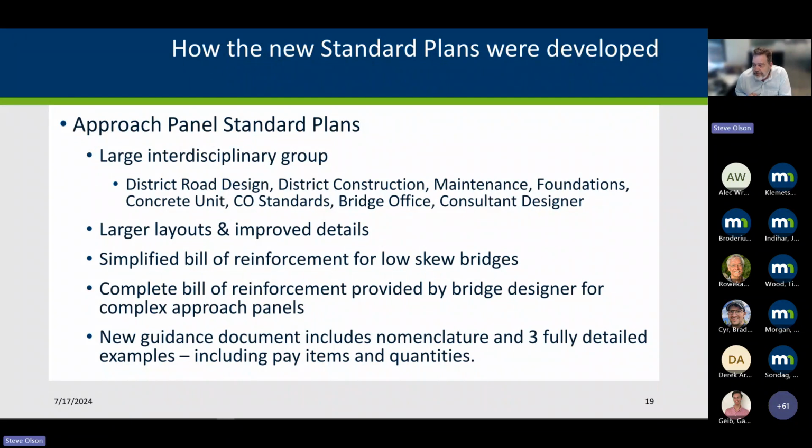The bill of reinforcement for low skew bridges and zero skew bridges is simplified. A complete bill of reinforcement will need to be provided by the bridge designer for larger skew bridges. And we've got 3 fully detailed examples, including pay items and quantities, in the guidance document.